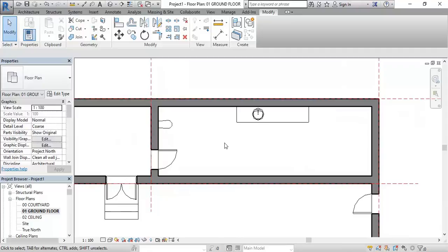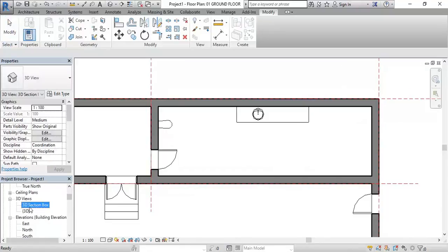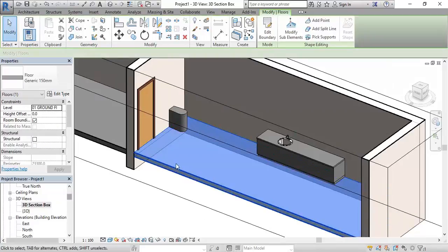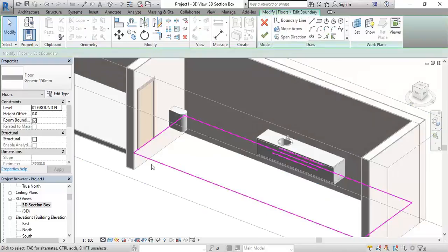Yeah. Well, actually, okay, so it's the same idea. Once you get used to using the tools like extrusion, say you want to do a cutout in your floor. Okay, I'm going to select it and show you how easy it is. Edit boundary is going to take me back to the sketch, so just like an extrusion.